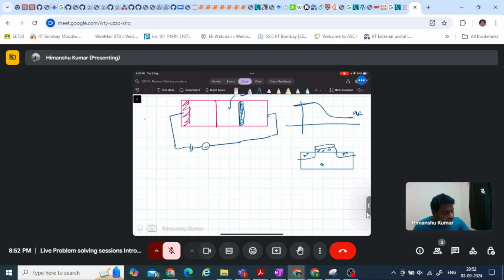But here, this PN barrier forms. If you are applying a positive gate bias, the surface potential of the p-type substrate will increase. So you are forward biasing this PN junction, and this barrier will become lower and inject a charge. This does not have any frequency limit because this n plus region has a huge pile of charge carriers.